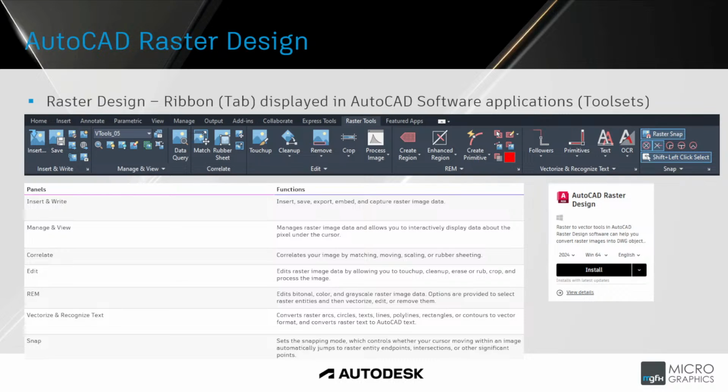In the panels from left to right, which are displayed on the screen, you have the Insert and Write panel with its functions for insert, save, export, embed, and capture raster image data. The following panel, Manage and View. This manages raster image data and allows you to interactively display data about the pixel under the cursor. Correlate correlates your image by matching, moving, scaling, or rubber sheeting.